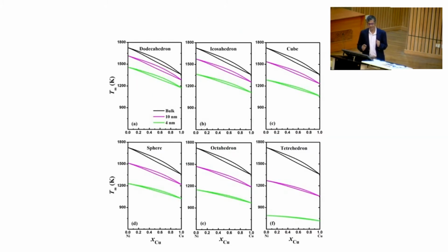Not only that, I also discussed, and we may come back one or two lectures later, that it is not only the size, but the shape of the particles also changes the phase diagrams. You can clearly see this is for copper and nickel. It's plotted the other way, with nickel on the left side and copper on the right side. Nickel has a high melting temperature. That's why it is looking like a lens, but another type of lens, meaning the orientation of the lens is different.